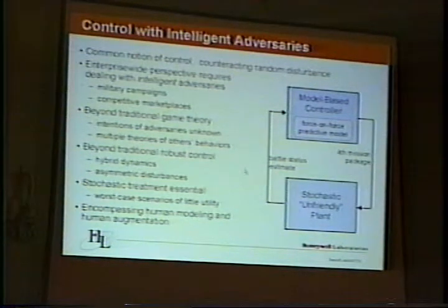And so you have this plant that's really a stochastic plant. On the other hand, your controller, if it's going to be any kind of typical model-based controller, isn't really going to be able to work with doing large-scale Monte Carlo simulations on stochastic plants. So you have to somehow abstract the behavior of the stochastic plant in some way that's computationally attractive.